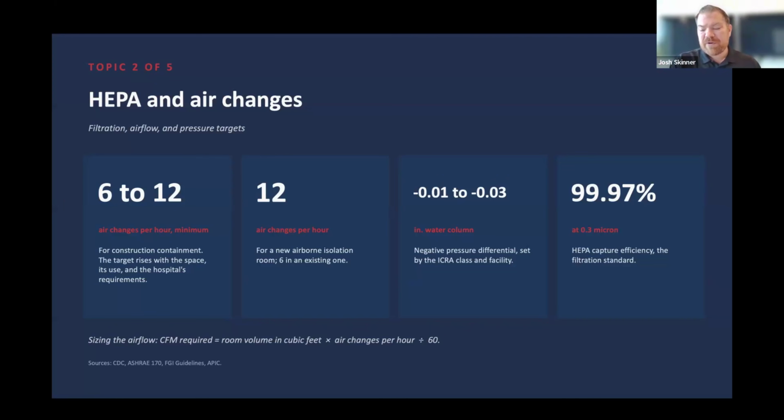Well, what most people don't understand is from day one, the moment you turn that machine on, you're officially clogging up the airflow. Every minute that machine's on, you're pulling in particles and you're starting to clog up and reduce efficiency. Most machines will have a little light that comes on and tells you. The problem is you're assuming that your contractors are looking for that light. We recommend a regular schedule.